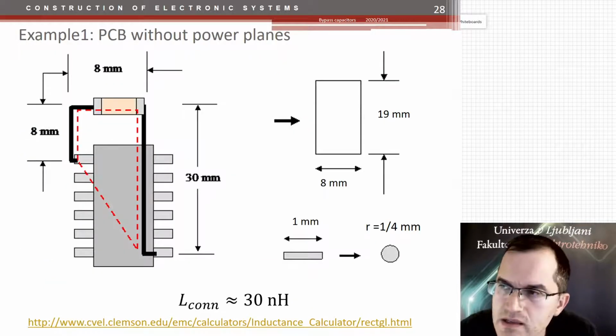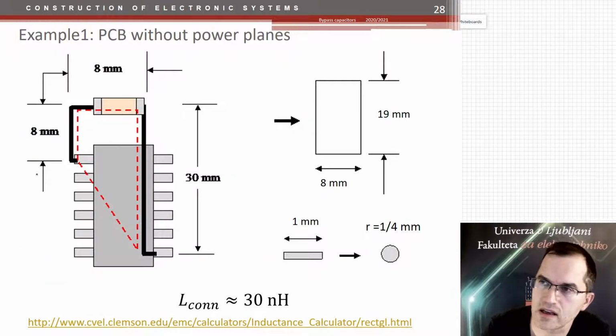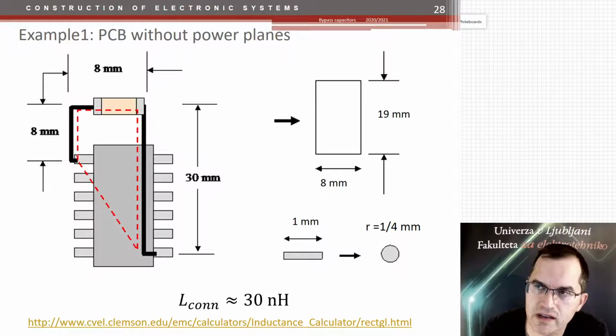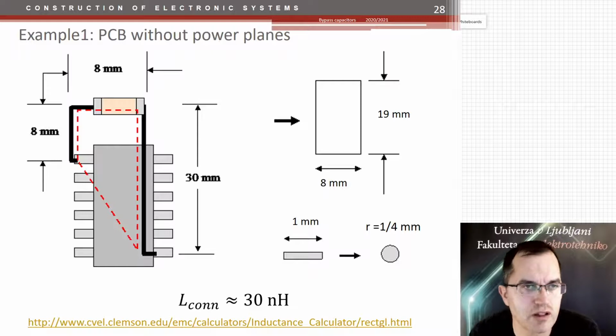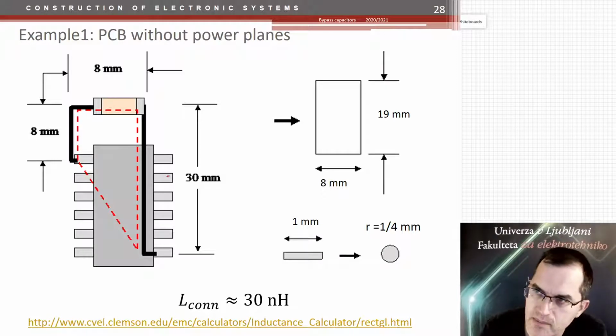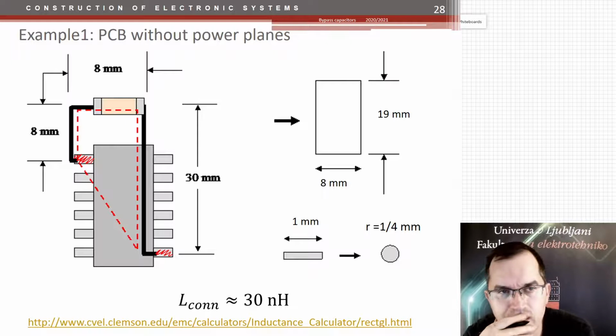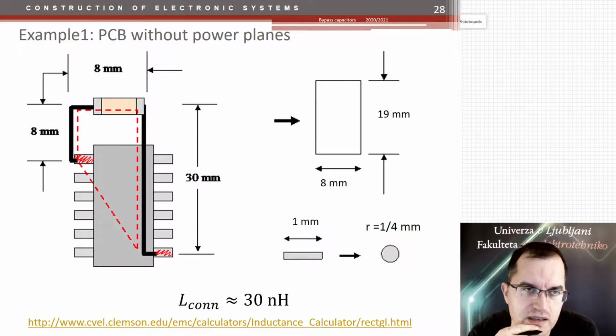First is using this integrated circuit and putting a bypass capacitor. This is a very standard digital logic integrated circuit. And usually it has power and ground somewhere on the opposite sides. This comes from a two-sided PCB's story where the connection of ground and power supply was the easiest by having this pin arrangement.